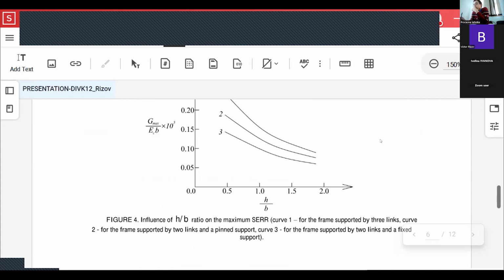In conclusion, it should be noted that the findings presented in this paper indicate that the strain energy release rate and the longitudinal fracture induced by periodic dynamic loadings can be regulated to a significant extent by the supporting conditions, actually by using some appropriate supporting conditions.